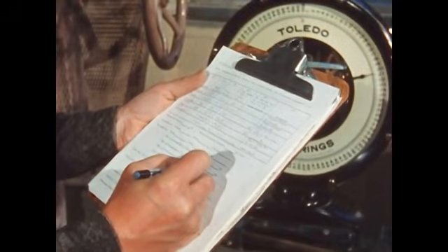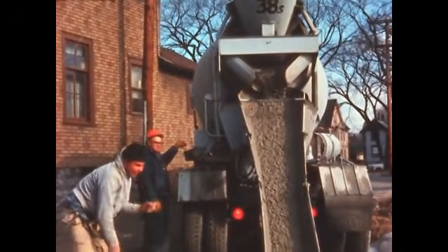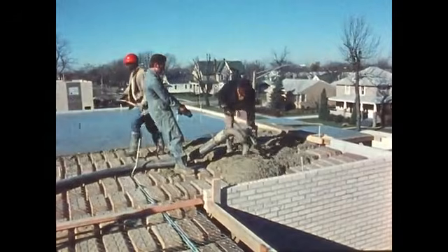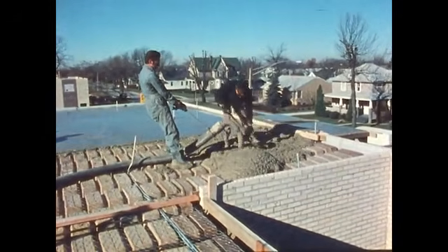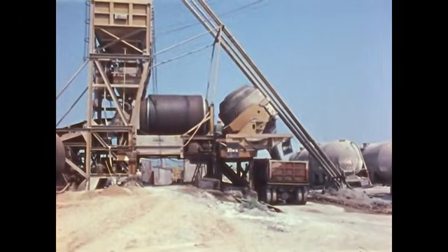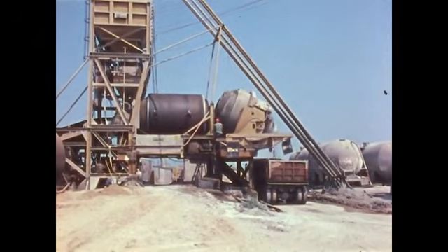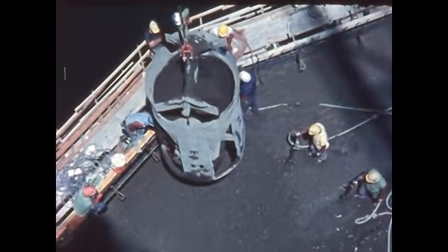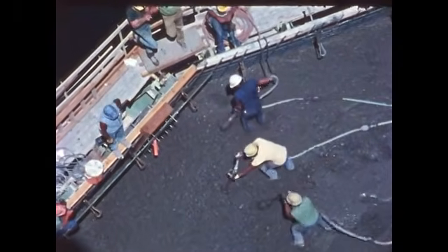Remember that the quantities determined in the lab will almost certainly require some adjustments in the field. Moisture content of the aggregate must be considered, as well as the presence of chemical admixtures and pozzolans. Temperature and humidity will have an influence, as will the size and type of mixer employed. Such changes as required will not affect the quality of the concrete, as long as the water-cement ratio is maintained. The result is quality concrete, designed to do the job.